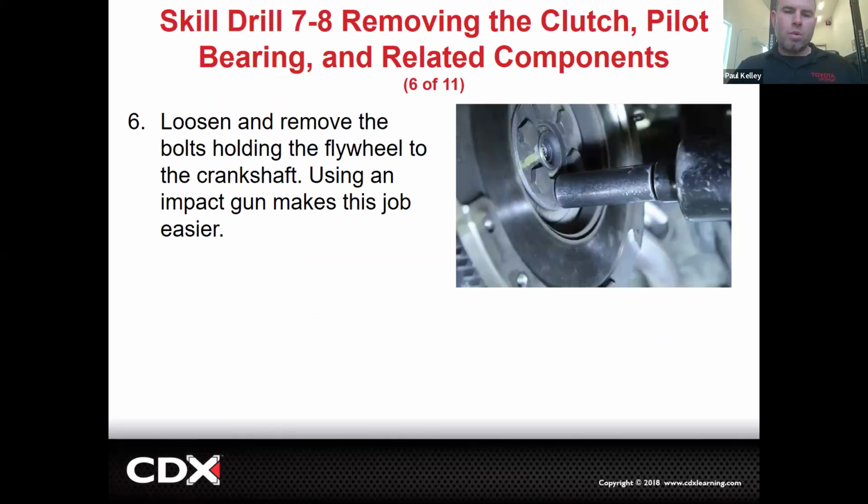So how to do that? Well, let's just say we're going to do clutch service, 11 slides right here. I cut some of them, but if you're going to loosen the flywheel, for example, do you notice there's a match mark right there? That's a best practice, just in case the engine and the flywheel have been balanced as an assembly, which wouldn't really be that common, but you could. So make sure we mark that.